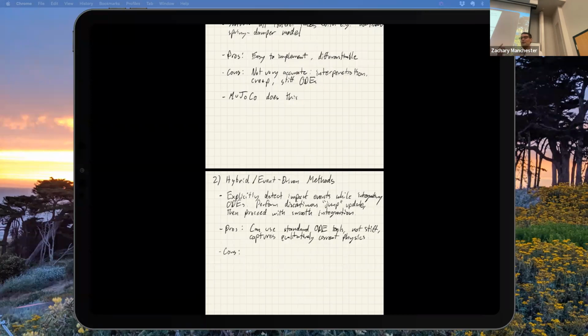So point feet, excellent. If you're talking about manipulating some complicated geometric object in a hand, where there's really an infinity of possible contact configurations, I can grip it a bajillion ways and the geometry is really complicated, then the number of possible contact modes just blows up and it becomes nearly impossible to do this in practice. So good for 4 point feet, bad for continuous contact geometry with a complicated hand. I would say these are very popular for legged locomotion, not very popular for manipulation.